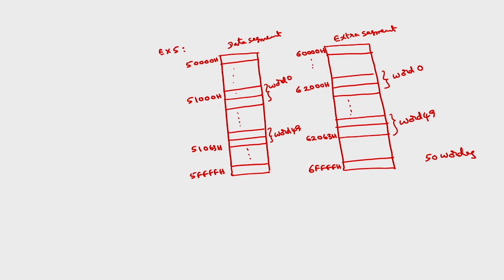For example, if you have 3E3F here and this is also 3E3F, after the first comparison itself you have to stop. Otherwise, if the two 16-bit words are different, you have to go for the next comparison. So we have to stop at a point where both words match, is one condition, and the second condition is if the end of the array is reached.